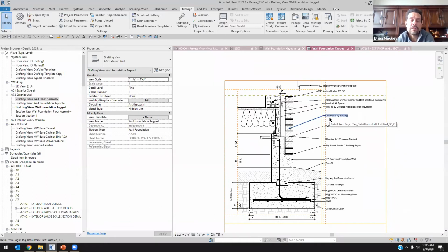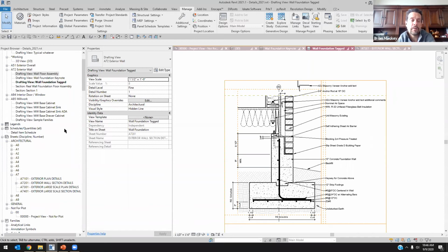So my personal opinion is, there's actually two ways. I have another way to nest or link details themselves into projects. I either keep all of my details in a separate file that I can link in, or I have details just in a separate file that I copy and paste across. You are going to run into the problem in Revit that when you copy and paste, you're going to start getting detail component 2, gypsum wall, board, bound, footing, whatever.